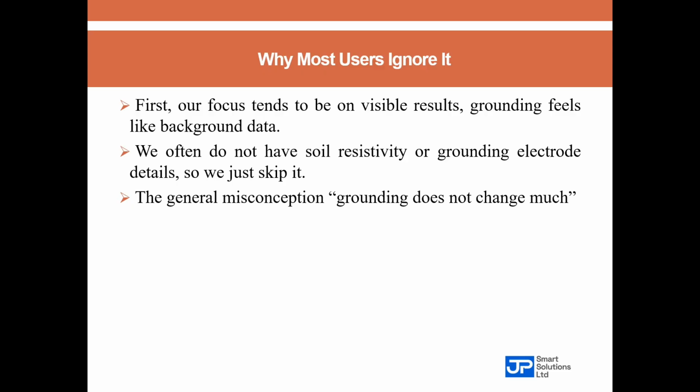So in this case, when we ignore grounding, we end up using default grounding types of equipment, which may not reflect the real system at all. That is why you can carry out a short circuit analysis, and what is in reality is quite different from what you have in your simulation. And this can lead to dangerous assumptions when those results are used for protection settings or arc flash labeling.